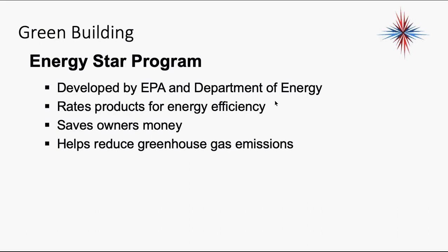It only is appropriate, and this again comes into the installation thing, your appliance or your air conditioning system is only Energy Star compliant if it's properly sized. In other words, it meets the specifications of the house or building, and it is properly installed. Those are the key. If it's not properly sized or properly installed, it does not meet Energy Star compliance. So again, be careful about that.